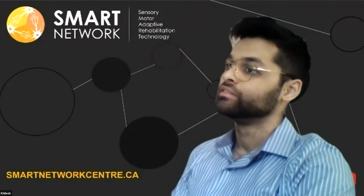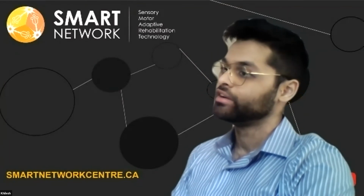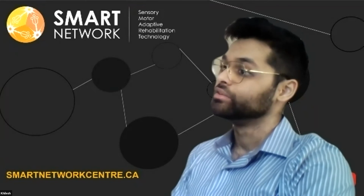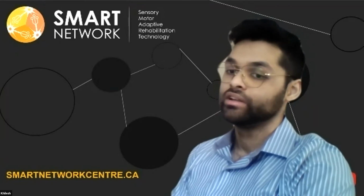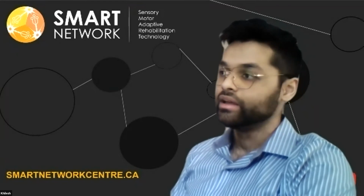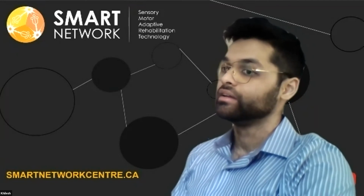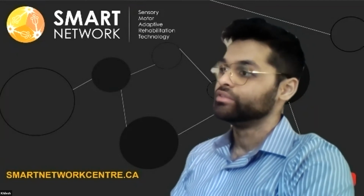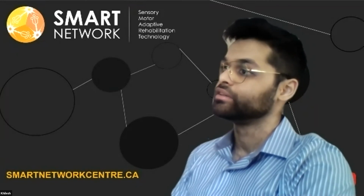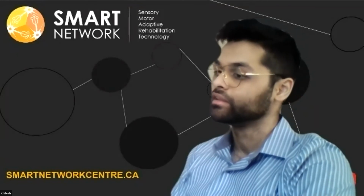It says here, Zigbee defines a network layer above the 802.15.4 layers to support advanced mesh routing capabilities. So it's just another communication algorithm. I'm just using their API, and there's no problem with data rate. The receiver just receives the hexadecimal through the USB, puts it into the software, and there are no issues with frames dropping or anything like that.